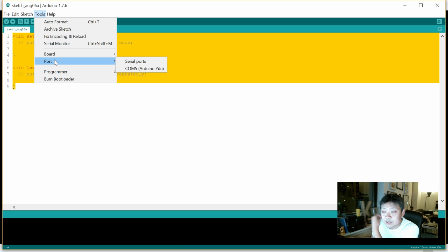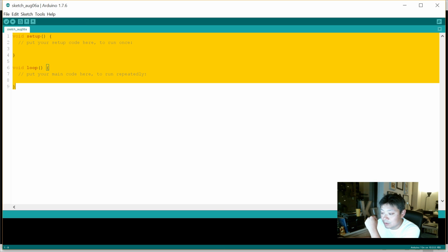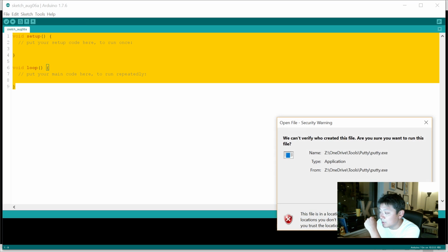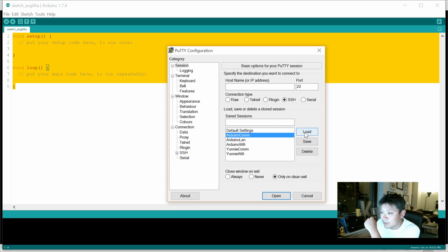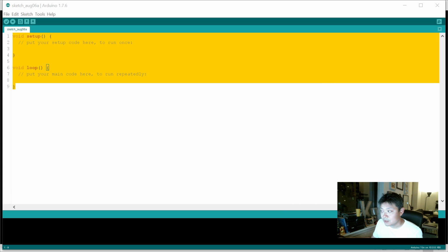And what we're going to actually try to do is hit it before the actual Linux OS boots up, because we're going to do some magic there. So let's go and open up a brand new PuTTY. All right, and instead of choosing the IP, we're going to choose the COM port. Fantastic. So let's open it. Alrighty.